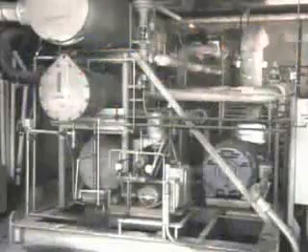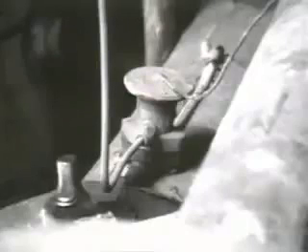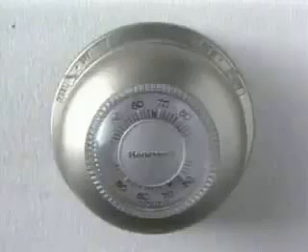In many systems, refrigerant flow and therefore the amount of cooling is controlled by an expansion valve. The position of the expansion valve is controlled by the temperature of the substance being cooled. Some control systems use a thermostat located in the area being cooled to position the expansion valve. Other systems may use a thermal bulb or a thermocouple.